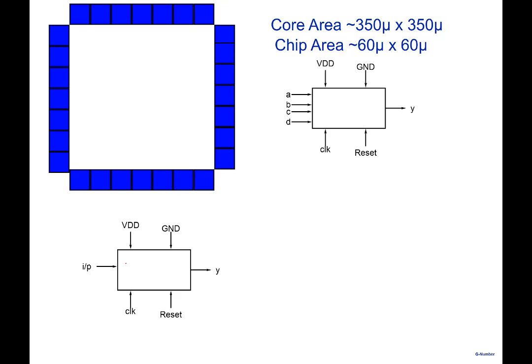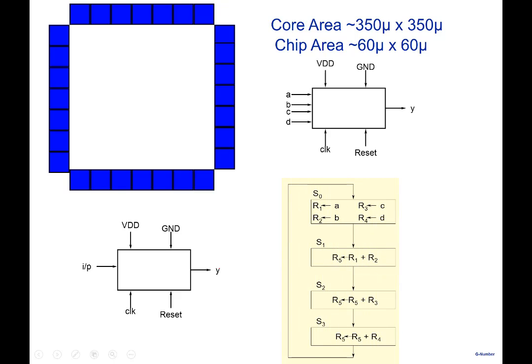to read the data. Earlier you could read A, B, C, D all simultaneously. Now you will require 4 clock cycles to read all the particular data here. But if you do that and we recalculate, this we were doing in parallel. But if you are willing to pay some price for it, then note that the number of pins would reduce to 4 here, and 6 here, 6 and 4, 10, 11, 12, 13, 14. Right, 14 pin. And 14 pin packages are available.